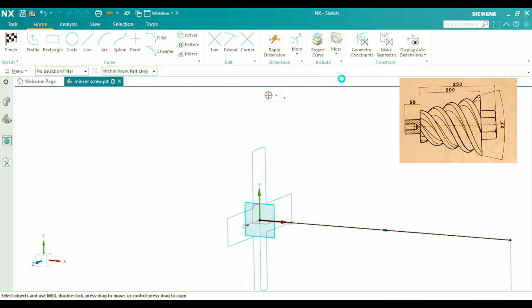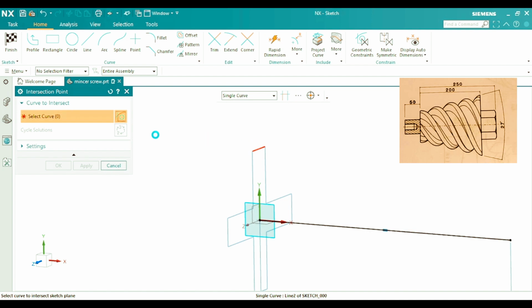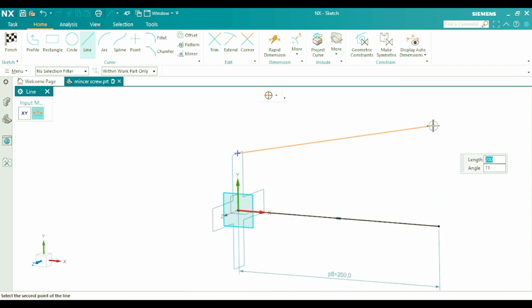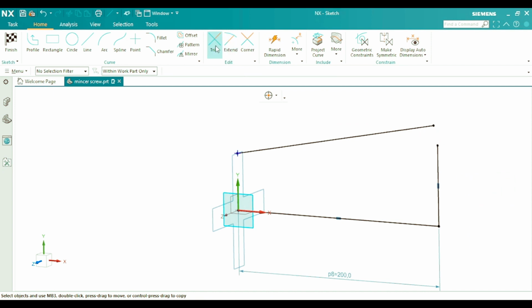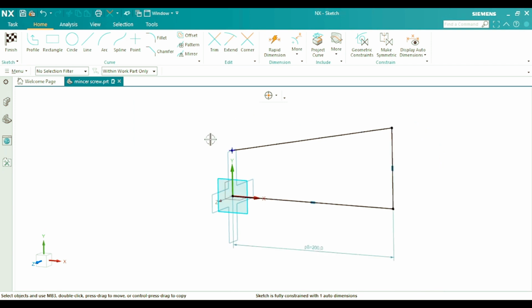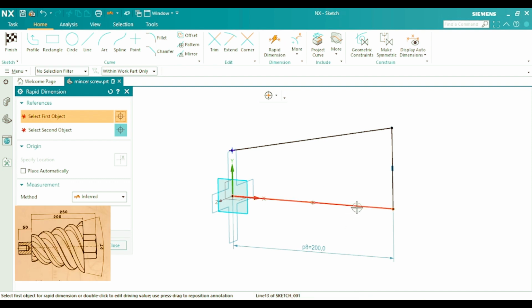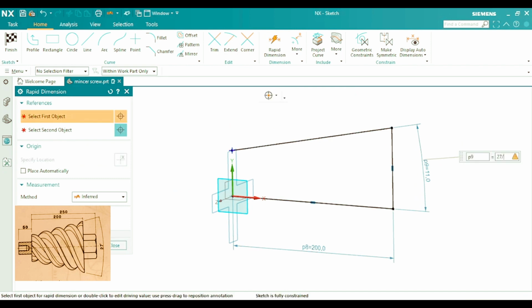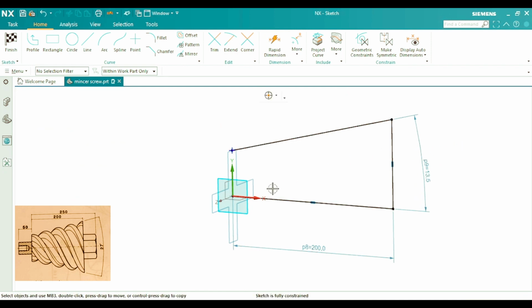Now we will generate the intersection point of the blade profile and the datum plane. We will find the start point of the angular line. We will be using this line as a law curve. We will see the detailed application later. For the time being we will draw the line and extend it to the horizontal line we drew before. The included angle is 27 degrees, so per side angle is 27 halves. This completes our sketch, and now we will start the solid model.